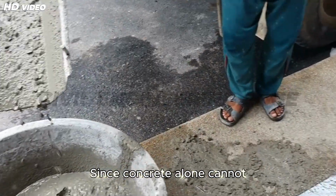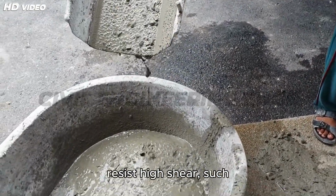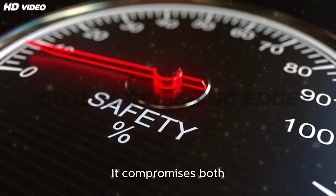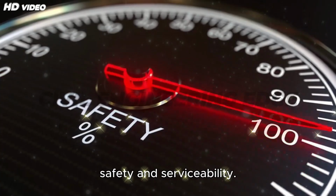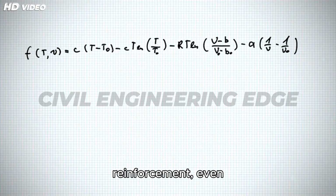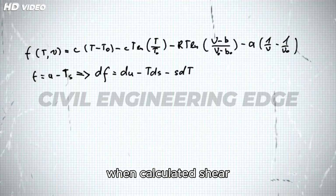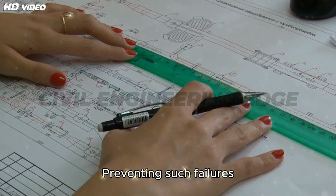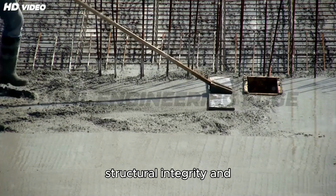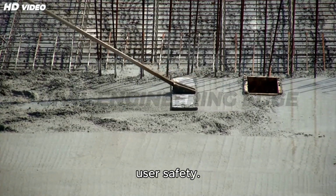Since concrete alone cannot resist high shear, such failure is sudden with minimal deflection or warning. It compromises both safety and serviceability. This is why IS codes mandate minimum shear reinforcement, even when calculated shear stress is low. Preventing such failures through proper design and detailing is vital for structural integrity and user safety.